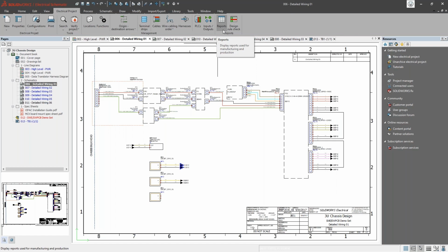This is all information, metadata, that you can compare within your project to make sure that you're getting the proper output. Do you have too many wires going to one pin? Maybe you have a 14 gauge wire going to a contactor that can only accept a 16 gauge wire, right? Those are things that we'll check for based on what you drew out in your schematic.